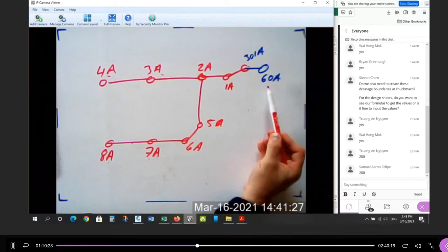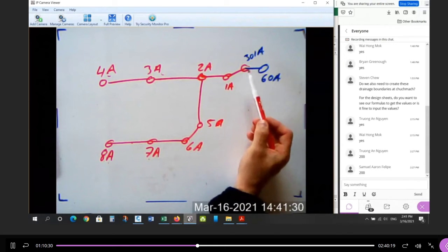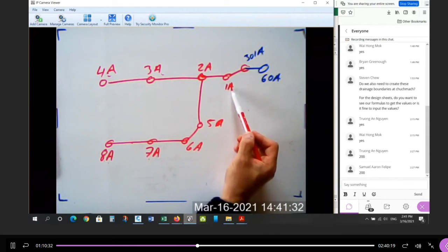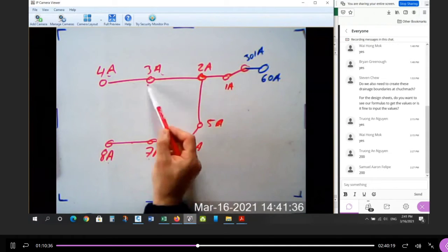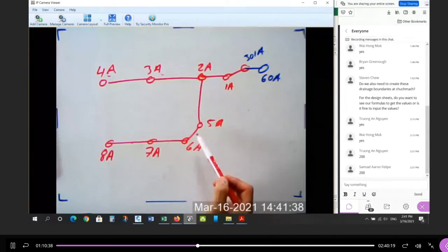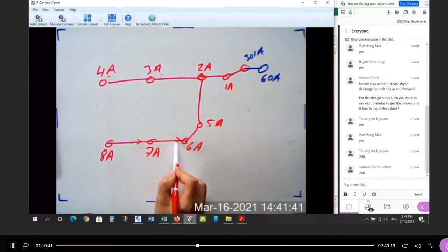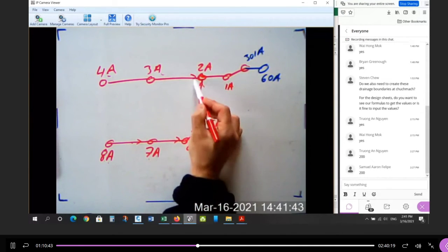So this is the system I expect you to use, right? Take the first two, leave the names. The first proposed maintenance hole is 1, go to the junction 2, and then go the least number of maintenance holes first. So 3, 4, and then go back and continue, 5, 6, 7, 8. And they're all flowing out, right? They're all flowing this way.